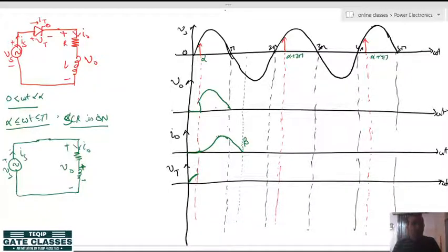Now, what about at the pi instant? As we have discussed earlier, at pi the inductor still has some energy with it. Because of it, the inductor L dI by dt will be very high, and until the inductor discharges fully or gets an alternate path to discharge, its polarity will reverse like this. It creates such a high L dI by dt that this thyristor has to remain turned on forcefully.